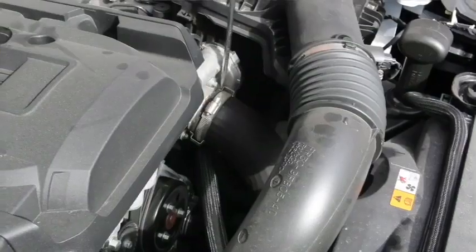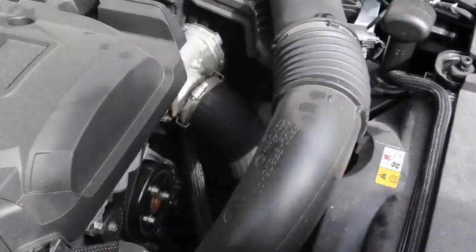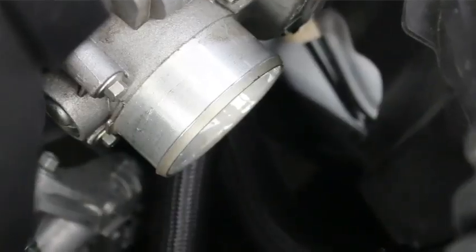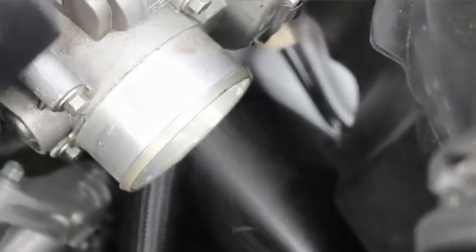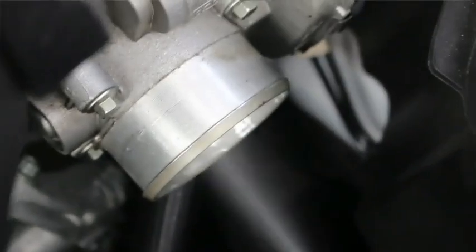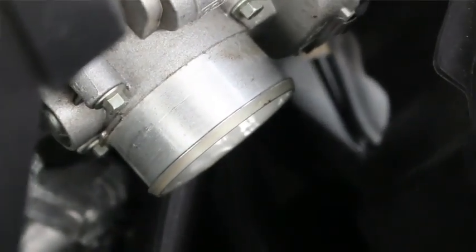So what we're going to do is directly shoot the cleaner into the throttle body itself, because we can remove the snorkel from the throttle body and the engine will run normal, and we can introduce the cleaner, making its way past the throttle body, through the intake valves, combustion process, cleaning the combustion chamber, the back of the valves, the spark plugs, the oxygen sensor, and even possibly cleaning the monolithic brick of the catalytic converter, and do a good cleanup job of all of this.